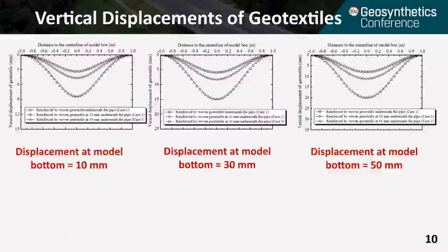But if you reinforce the pipe a little bit far from the pipe, even though the tensile force can spread the force, when the displacement transfers to the pipe, for the same reason, the layers between the pipe and the geotextile can still have displacement that influences the performance of the pipe.